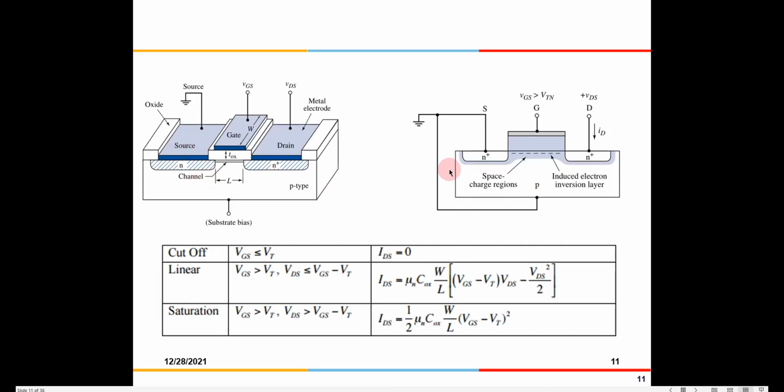Okay, now this is what is again shown here. When there is no gate voltage, IDS is 0, but we said IDS won't be exactly 0 because there will be some leakage current. Obviously there is something known as a threshold voltage, which you might have studied in your device classes. So VGS has to be greater than the threshold voltage; only then will this switch on. Whenever VGS is greater than the threshold voltage, the current will start flowing.